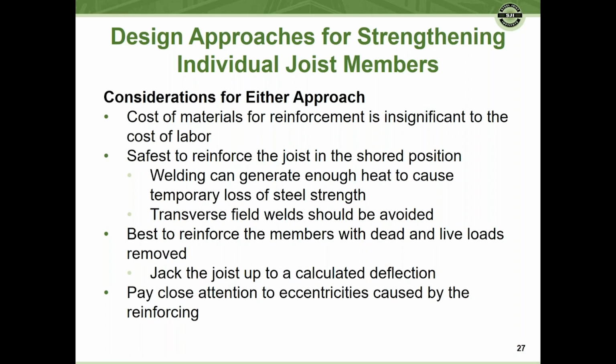Another is that it's best to reinforce the members with the dead loads and live loads removed. Sometimes that's possible, sometimes that's not possible. But you can jack the joist up to a calculated deflection to help remove the loads when possible, and then pay close attention to the eccentricities caused by the reinforcing. Those eccentricities can actually cause the joist to act a little differently than what our design assumptions are, so we need to be careful of that.